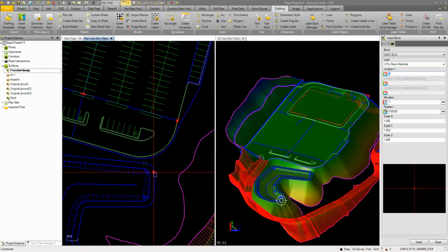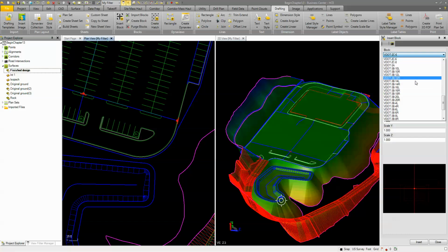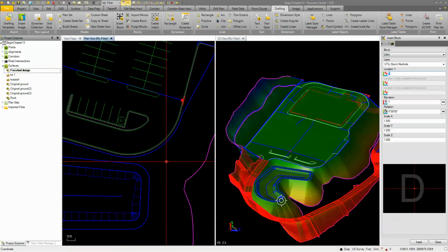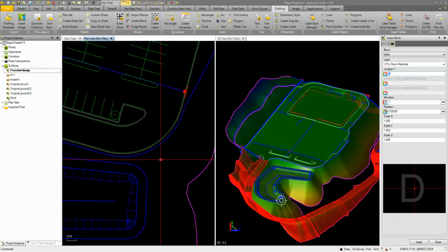We're actually going to have another drainage manhole or junction box down here. So let's put another manhole in, and that location, let's say, is up here. So we're going to go from here, and we're going to put it into our pond here. So we'll just go ahead and set him at that location. Grab that elevation.